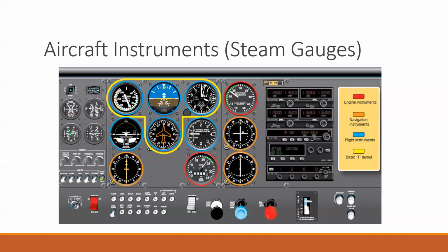For instrument flight, we do what we call standard rate turns. It's an exact, precise degree rotation, and then it's very calculable on a timer or whatever. You can calculate how many degrees you've turned based on the number of seconds that have passed in a standard rate turn. So that's what you use for that. As long as your wings are lined up with either that one on the right side or the left side, you're in a standard rate turn at 30 degrees of bank.